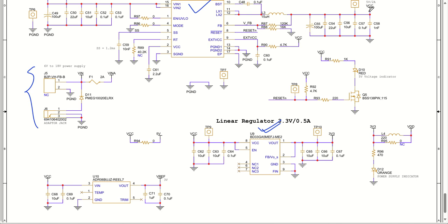So whenever there is no fault and this VCC is there, this particular LED will be glowing. Okay. If this particular IC shows any faulty condition or any problem, then this reset will go low, so this particular MOSFET will not be working, and this is how this LED will go off, and you will understand that okay, my 5 volt is not appearing on the board.